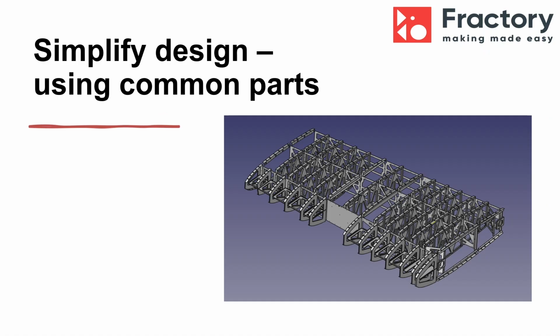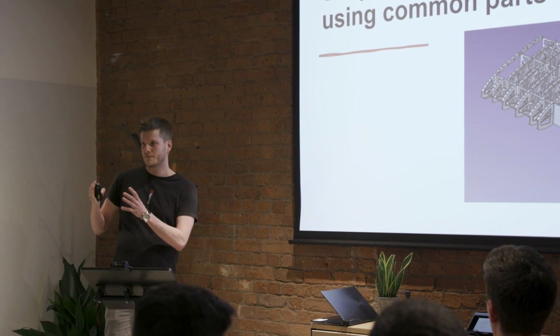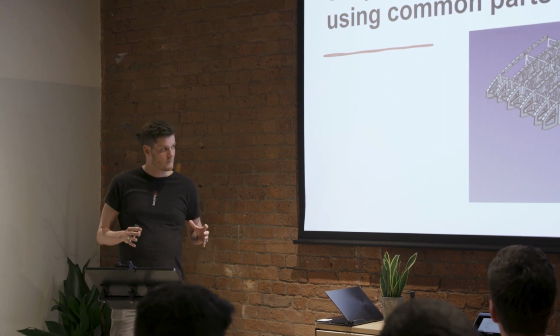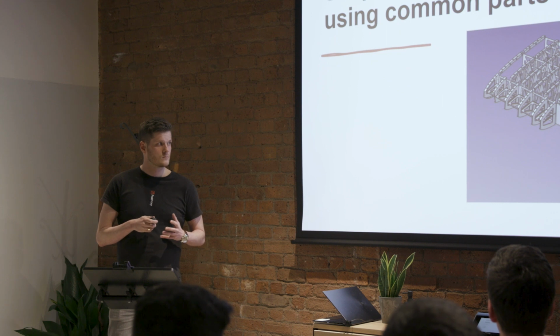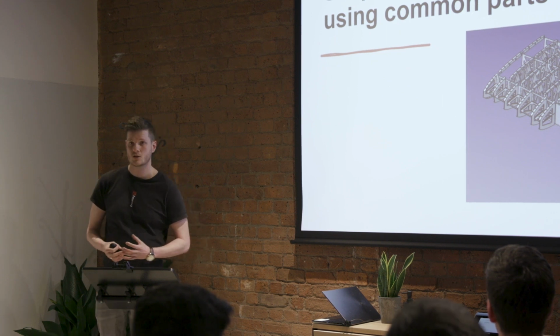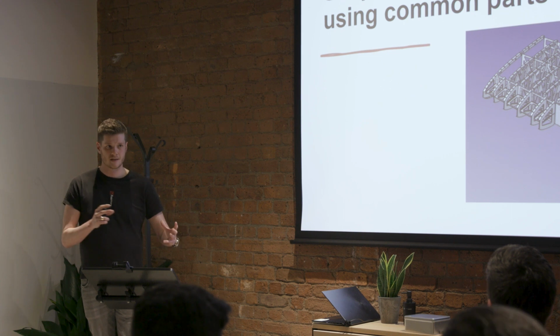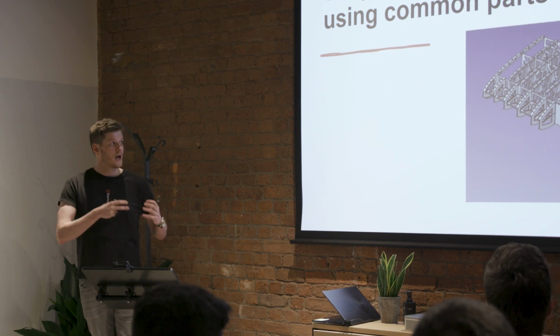Now, coming on to actually more towards assembly and designing your assembly and main components, and it's going into simplifying the design. You might not be able to see from where you are, but every single one of these pieces is unique, and there were quite a few of these different assemblies, all of them unique as well. Slight changes. This piece is slightly bigger than this piece, which is slightly bigger than this piece. Same with the flange lengths, bends in every component in there, making them really time consuming, just even that programming, making sure every single piece is nested up onto the sheet.